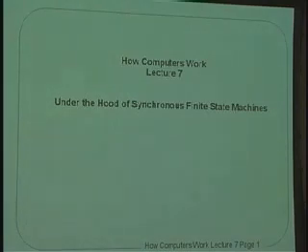So what we're going to be doing right now, in the last lecture, we took a general look at finite state machines, okay? And they were called synchronous finite state machines because the state transitions happened in synchrony with a periodic clock, right? Every so many billionths of a second, what have you, the system would transit from the present state to the next state.